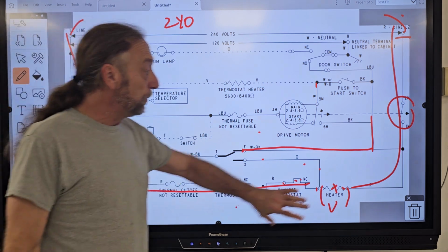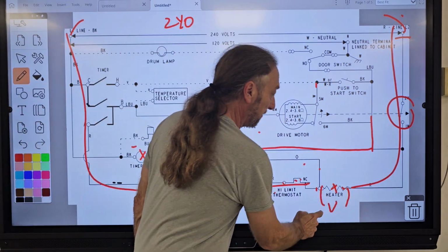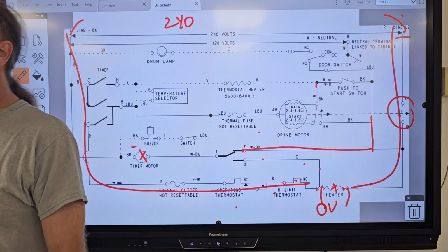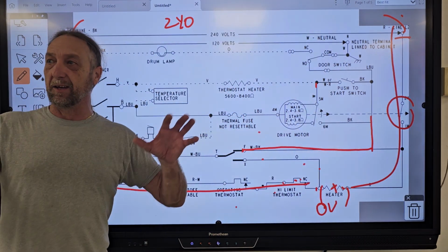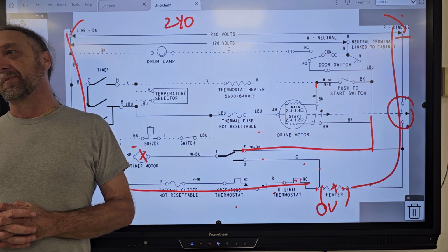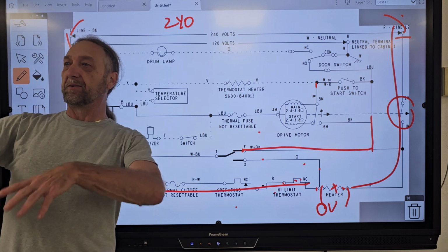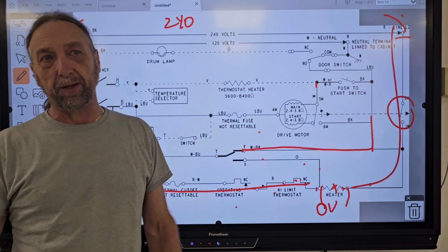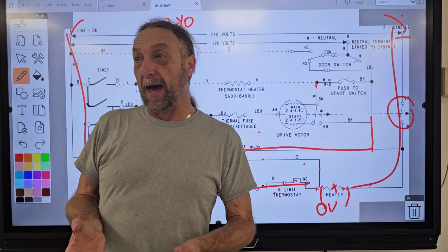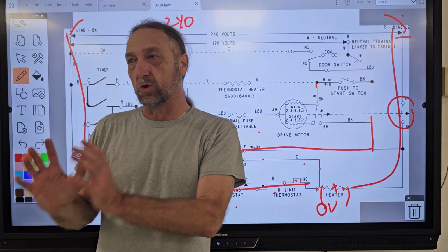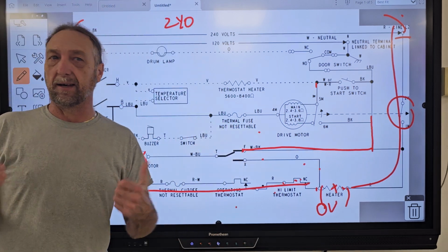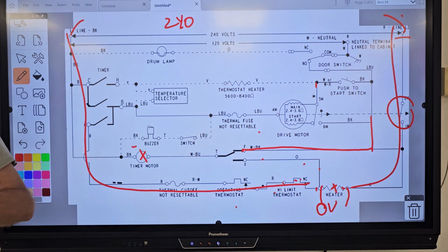So when we troubleshoot that, let's just say my meter said 0 volts. What do you mean by bad airflow? Well, if you have bad airflow, your element would start to sag and go bad prematurely. That's when the little filter. Well, yeah, you pull the filter out and see if you've got airflow there, but maybe the hose in the back is crushed, maybe the vent going out to the customer's house is bad. It's still heating, taking long to dry, but it shortens the life of your element. That's what I meant by that. The element just can't take that excess heat without that airflow.